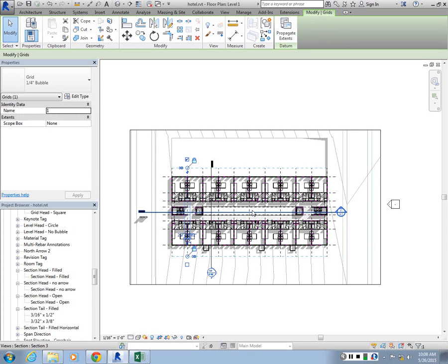I saw a lot of weird stuff happening, like sections have different colors, elevations have different colors. I give comments as well, but let's not use colors for orthographic sets. Let's just keep them black and white in grayscale. I want you to use shadows though, like add really light shadows, add black poches for cut elements. But for the rest, simple things.